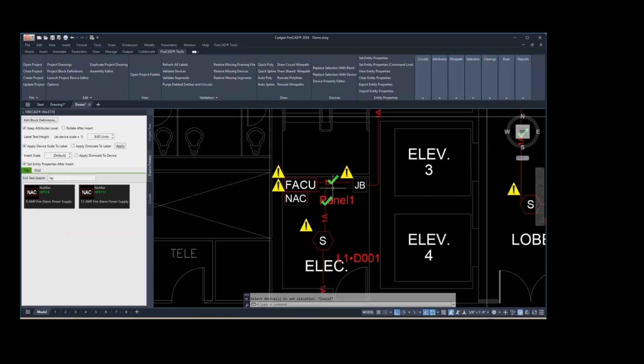And now I'm going to go to circuits, set active circuit from device, and I'm going to choose the, I think, is an RDP a legitimate output from a Notifier panel? RDPs. No, you would have to use a control module in this. How about a NAC circuit from the fire alarm?